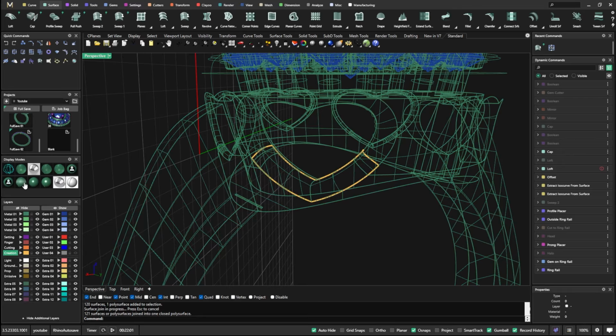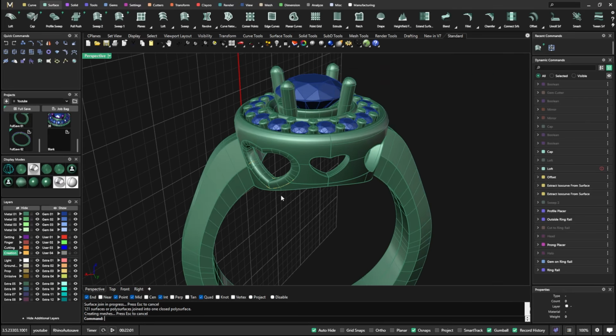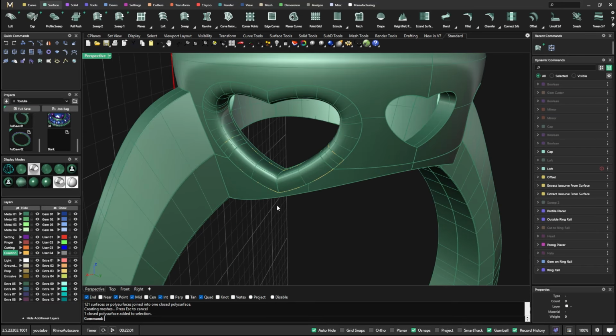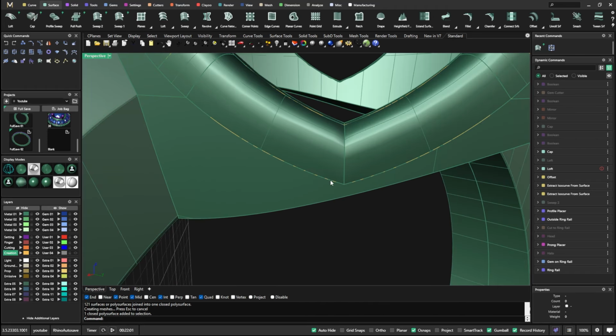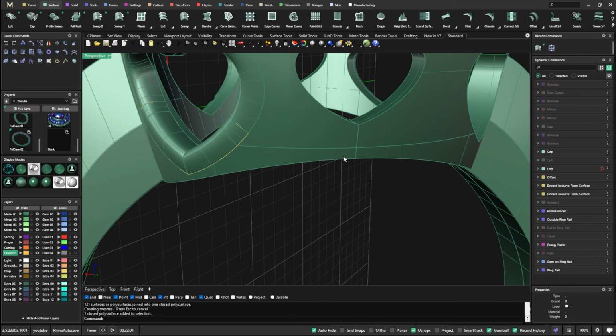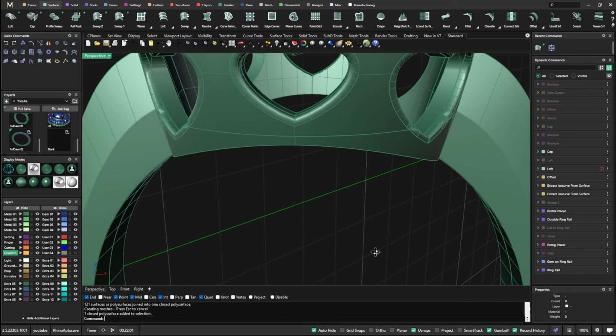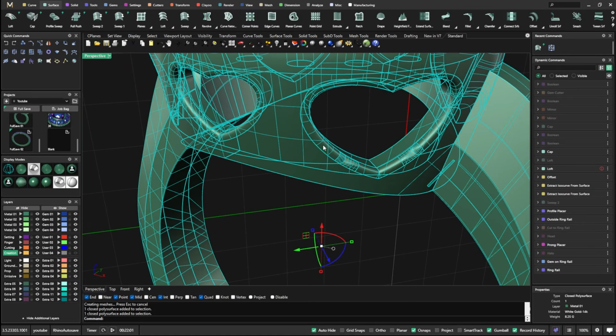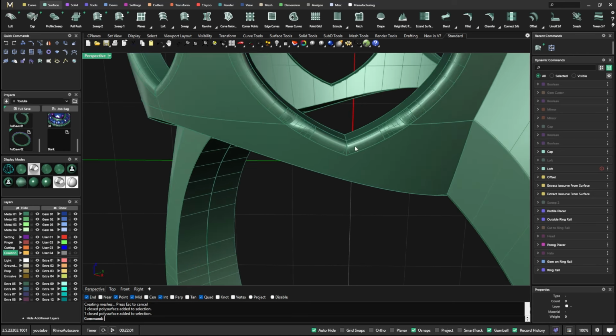And give it some shading and check it. Closed poly surface. So that's how you can fix that pretty easily. Plus it gives a nice little heart indentation there. I kind of like that better than I like this. Yeah, that's okay. Yeah, so you can explode it, delete those surfaces, dupe the borders, and use the rails